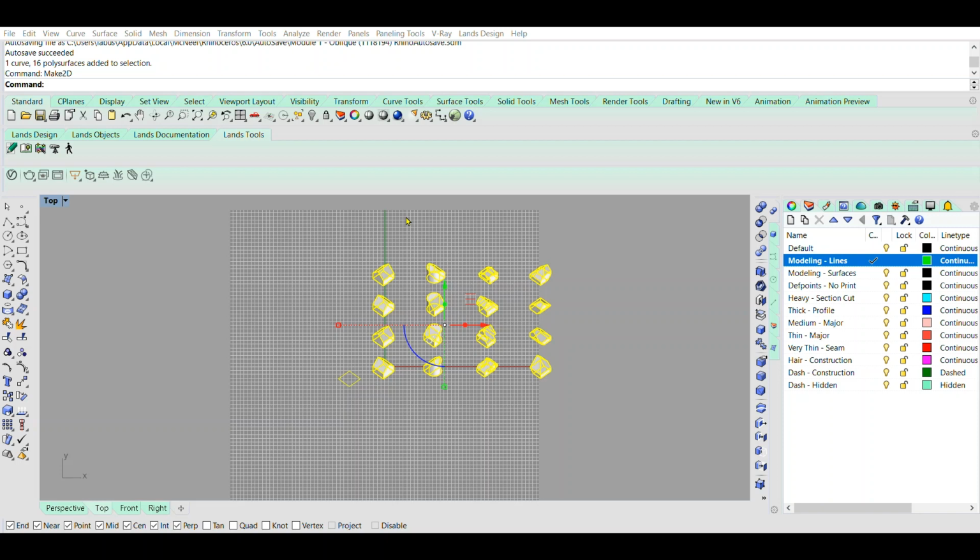Object properties, I'm going to keep it at maintain source layers. And then the options I want to keep on, I'm going to make sure hidden lines are on and scene silhouette is on. Scene silhouette is often called the profile as well, and that's kind of like what we call the thicker profile here, which is like the outline of the silhouette.